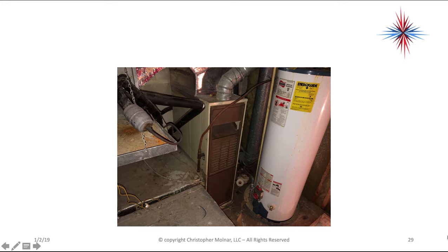Okay, again, we have a natural draft water heater sitting right in front of a very old return duct, and you can't see it from the picture, but this is a very loose fitting cover on the blower housing. So it's a very likely possibility that we are sucking some of the exhaust gases from the water heater back into the furnace.